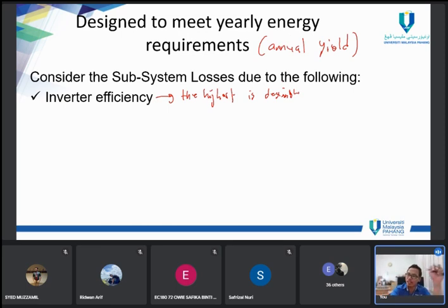So for the inverter, you can't just simply buy from the internet, click, use Shopee Pay for example, and just buy because it's cheaper. No, you need to be very sure that the brand is well established, they have the data sheet, the data sheet is correct, and they have experts you can contact, because you are playing with high scale. Grid connected, you cannot play just like that. Everything must be original. I mean the brand must be original, not the pirate one.